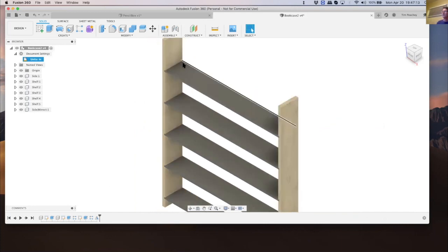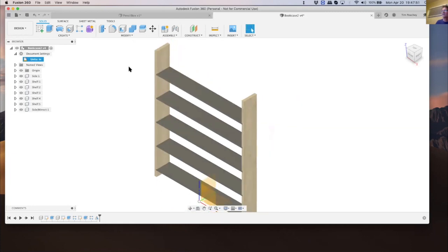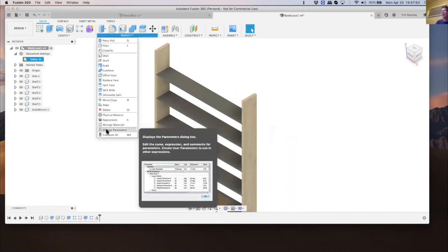So when I sketch the shelf, the end points align to the edge. Sometimes you'll do this and you'll find the shelf didn't change with it. Then you'll need to go into the initial sketch and add the constraints that you assumed had happened and didn't. So often I have to go in there and add a collinear constraint. I think that happened last week. So in the sketch menu, edit the sketch, and then add constraints to reflect the design intent. What else do we have for parameters?